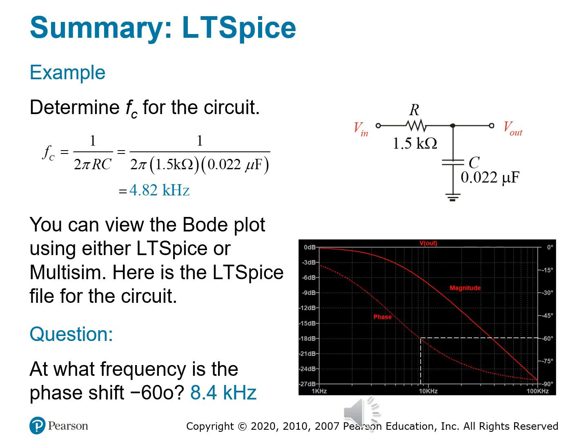And this is the frequency at which the output drops to 70.7% of the input, right where that negative 3 dB point shows up in our magnitude plot. Inside the Bode plot, the simulation window, that gives you two things. The magnitude response showing how the amplitude of the output drops off, and the phase response showing how the signal shifts in time. If you zoom in to that phase plot, you'll see a negative 60 degree shift right around 8.4 kilohertz. That's beyond the cutoff, where the lag gets more pronounced and timing begins to really matter.